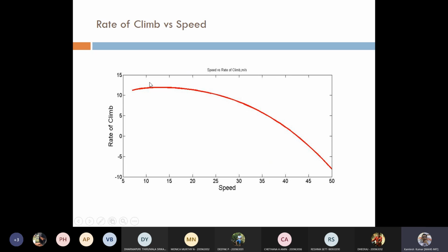Rate of climb is sometimes very fast, sometimes very slow. So what rate of climb is going to be supported by the aircraft, either for the structure or for your sensors and electronics themselves? Okay, it also should be analyzed. This is not like a fixed value, correct? This can be different for different aircraft.